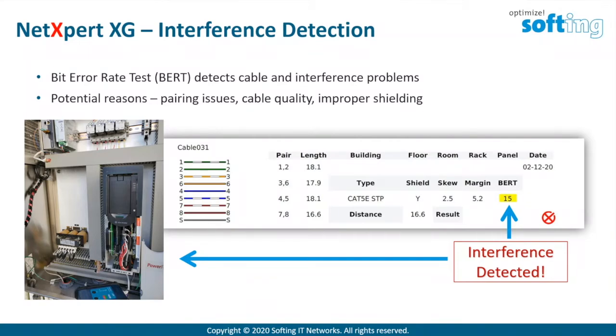The test results showed that though the cable passed the wire test, it did not pass the 1 gig test for bit errors. So this was an indication that though the cable was shielded, it wasn't shielded enough, or the shield was damaged somewhere in it. And after a year of problems, they replaced it with a higher grade shielded cable, and that fixed the issue of that pump station going offline.